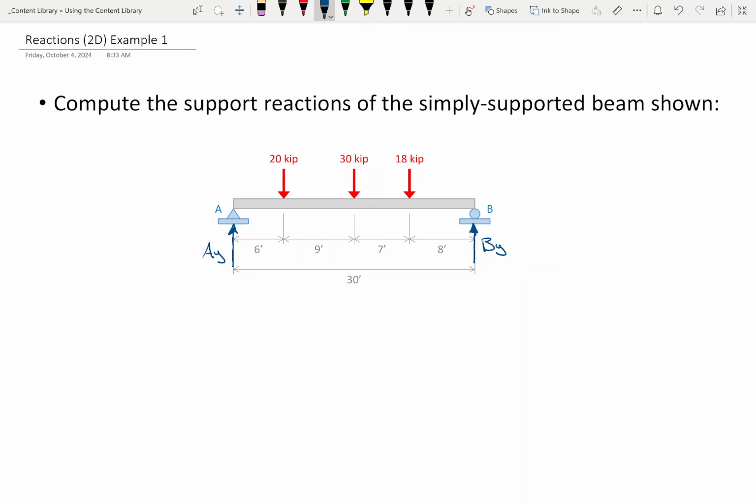What's going to happen is we're going to go through the calculations, and if you guess incorrectly, your answer will be negative. So, oh, I just guessed the wrong way. And does that comport with what we've been talking about so far? Well, yeah, think about it. If I have a force that's acting this way, and I tell you that force has a magnitude of negative 20 pounds, that just means it's acting this way, right? It just means it's acting in the opposite direction. So we're guessing that the force acts this way. If we get a negative, just flip it, okay?